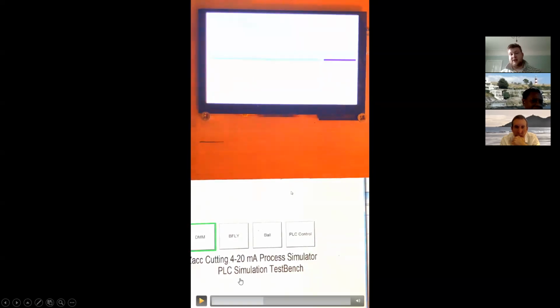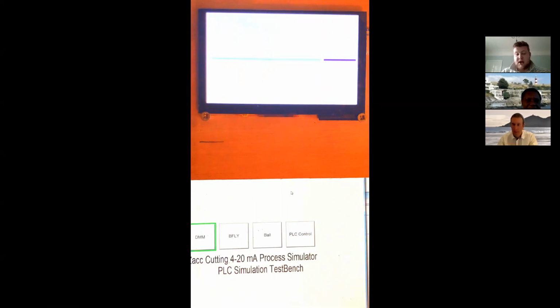I'll just pause that there because it just shows off a couple more. I'm conscious about the time. So basically what I'm trying to show in this video is all about the indirect addressing. So instead of having safety information pages, one page that prints each and every time, I'm basically printing a shell for the page, and then through the use of case statements and indirect addressing, it's then populating that with the data that we called for.